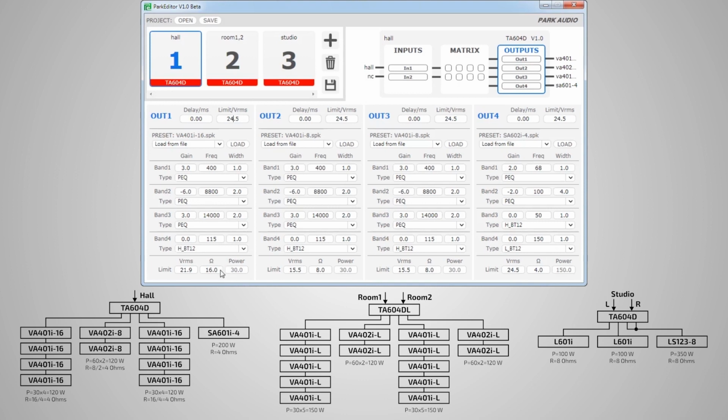To set the limiter, enter the value of the impedance and the amplifier output voltage. In the right window, we obtain the value of the output power. Changing the value of the output voltage, we can easily pick up the required power. Previous configuration settings.